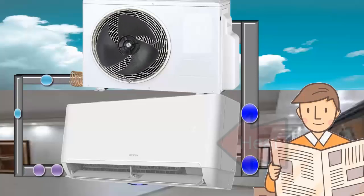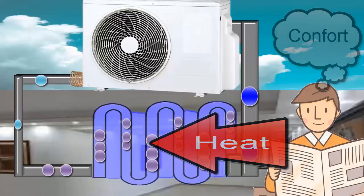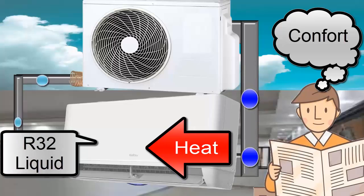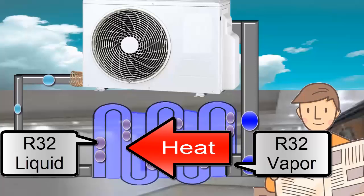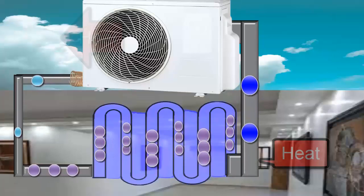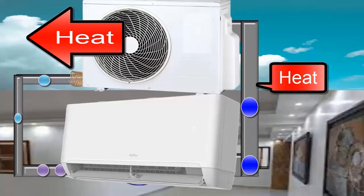Let's remember that the heat from people is absorbed by the R32 gas, providing occupants with a sensation of cold and comfort. This heat causes the R32 in the indoor unit to boil, meaning it changes from a liquid state to a vapor state. The heat absorbed by the R32 must be expelled outside for the system to continue cooling the premises.